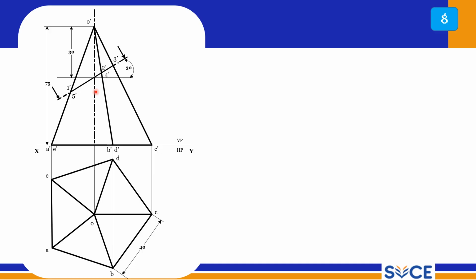So here students, you should be very careful. As per the principle of development, we have to take only the true length. So which is the true length line? This is not a true length line, this is also not a true length line, only OC is the true length line, since OC is the slant edge which is parallel to VP. Only this slant edge will give you the true length. So all the points should be projected onto the true length line.